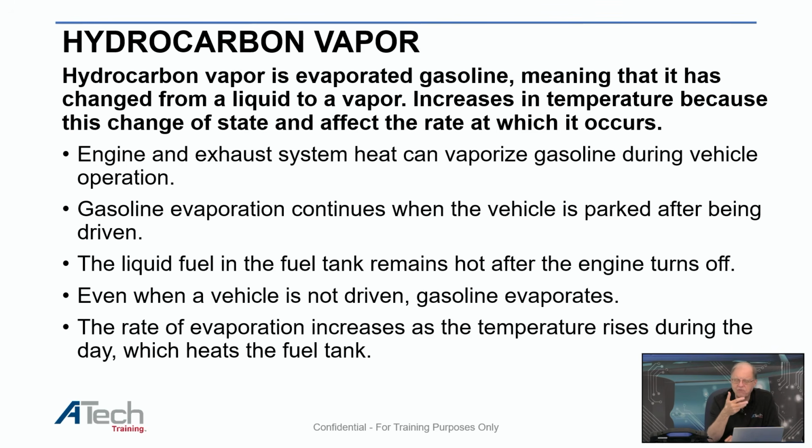Even when the vehicle is not driven, it says up here gasoline evaporates. That's true. If you don't believe me, just take a gasoline tank, put it out, and just let sunlight get on it over a period of time. You will see it expand. And if you take the cap off of it, you'll see the pressure go away, like you're doing when you're getting ready to mow the grass. The rate of expansion increases as the temperature rises during the day, which heats the fuel tank. So that's part of the reason why we have the engine off natural vacuum system also.